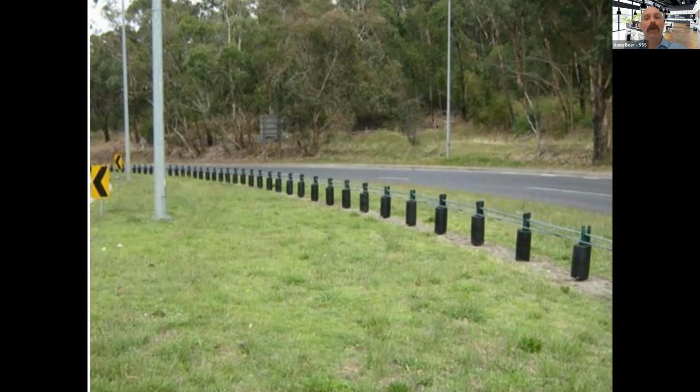So maybe if you're doing a big route and you've got one particular spot where you're concerned about motorcycle safety, or the motorcycle community is jumping up and down about it, you could retrofit some of these just to sort of alleviate. Really though, if you agree that it's a motorcycle risk at that location, switching your barrier system to something you can fit an underarm protection as you go.